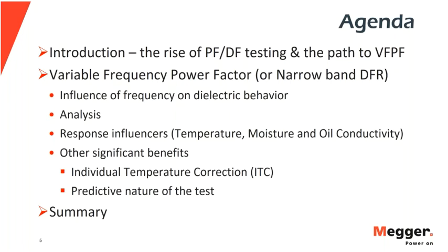Since narrowband DFR is a repetition of tests that is performed each time with everything held the same except for the frequency of the applied test voltage, we will first talk about the influence of frequency on dielectric behavior. And with this knowledge in hand, we will review some proposed analytic guidelines to interpret the narrowband DFR test results. From there, I'll share some helpful thoughts to illustrate how certain parameters, namely temperature, moisture, and oil conductivity, influence your